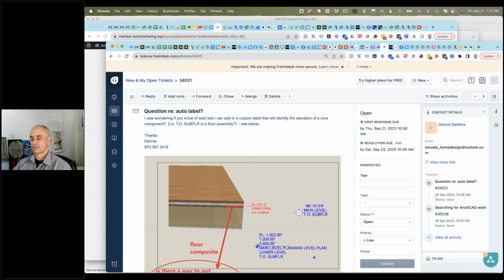So I'm just looking for something where you could take basically a concrete floor and add a topping. But I know it's not available right now as a standalone tool anyway. Well, when I think about that context, flat bottom, different point elevations on the top, the mesh tool is actually ideal because it does have a flat bottom, and part of the functionality of the mesh is that you can say this point here is at a certain height and this point is at another height, and it will just figure out the top surface. So it is a natural thing.